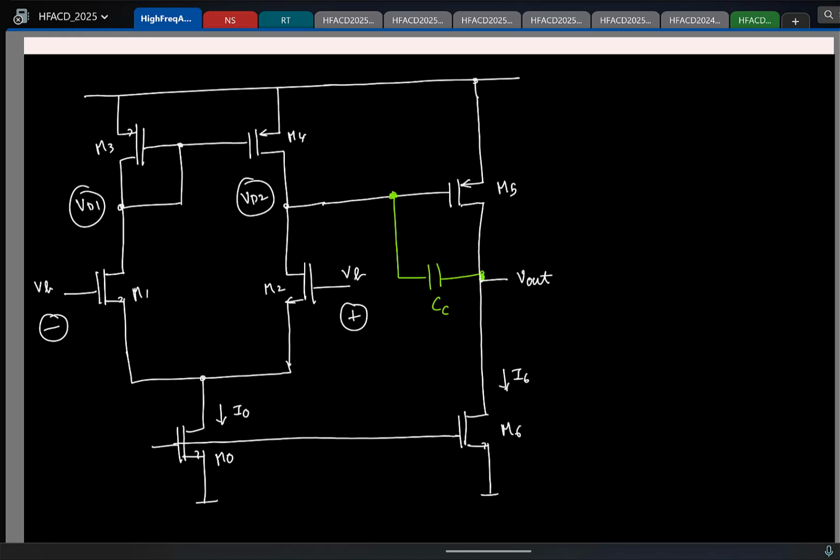I mean, if you recollect, this is a problem set I gave you in the third practice set. Let us say you have two current sources like this. Remember that I have a PMOS transistor whose source is fixed, gate is fixed, so it is acting like a current source. NMOS transistor is here whose gate is fixed, source is fixed. It is acting like another current source. Let us say even magically, by luck, I made sure the two currents are equal, say some IX and IX. Both are equal. Then what can you say about this voltage? It's not defined. This is a problem I gave you to work. So this is not defined, right?